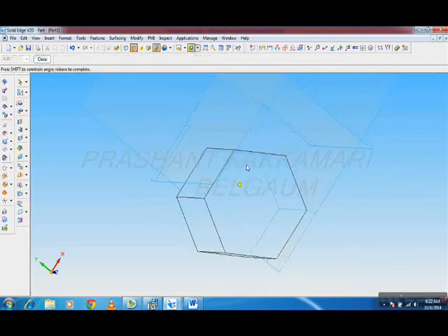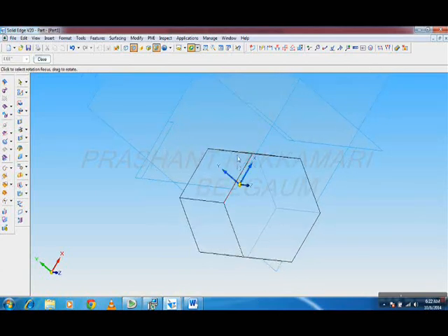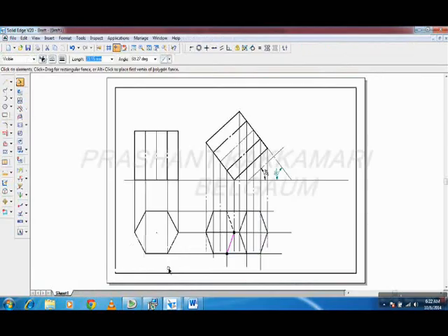If you are still confused, it is like this. These all lines are merging here, visible, invisible, everything. Okay. Now A to B is invisible. Okay, I have done. From A to this line is A to H. A, B, C, D, E, F. Okay, F. So A to F is also invisible. So draw it by hidden line. So this is over.